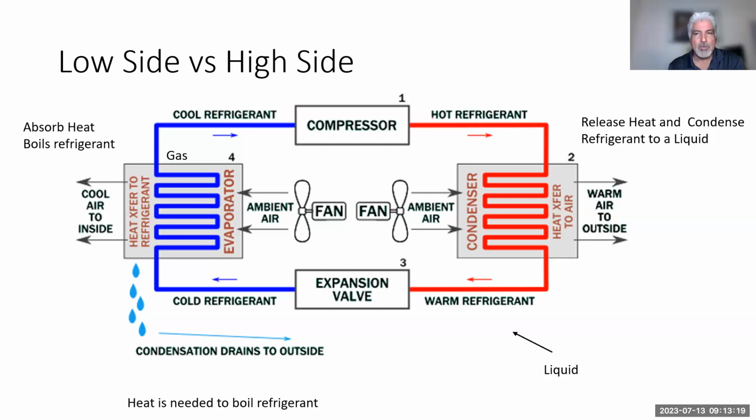Like we mentioned in part one, there are basically two styles of refrigeration systems: the expansion valve type and the orifice tube. Ford has been known to use the orifice tube in the early vehicles, and now they're using expansion valves. GM is the same thing. They've been using orifice tubes, but have also moved to expansion valves on certain models. So it can vary. The imports like the VW TDIs and so on definitely use expansion valves as well. But we're pushing up against this.